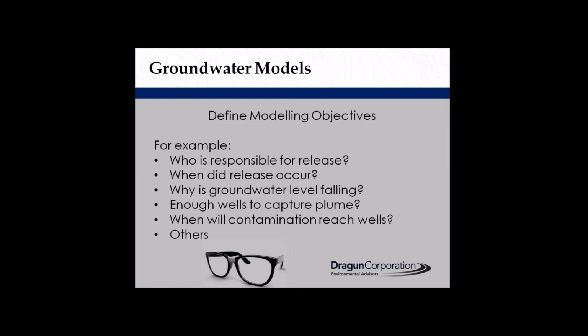We've also used models to help justify a monitoring frequency that might be a little less often than what the regulators typically would shoot for. The default that you hear from most regulators is they want quarterly monitoring. Well, a lot of times that just doesn't make sense for how fast the groundwater and the contaminants are moving. So we've used models to justify monitoring frequency as long as 3 years.